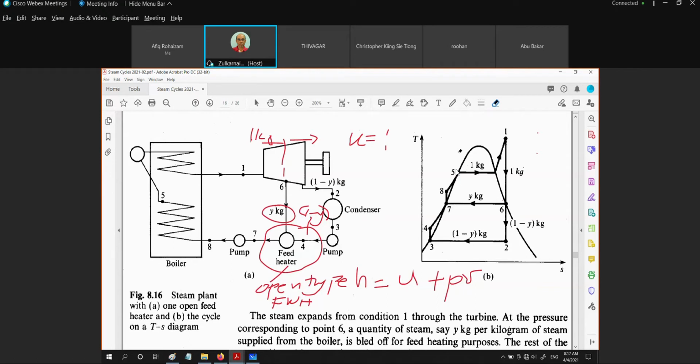As though we are trying to get as isothermal as possible the process 8, 5, and 1, as what we can see for the Carnot cycle. Okay, so we are going to increase or to average it up to a higher value. So that's why we can increase the thermal efficiency of this type of cycle.